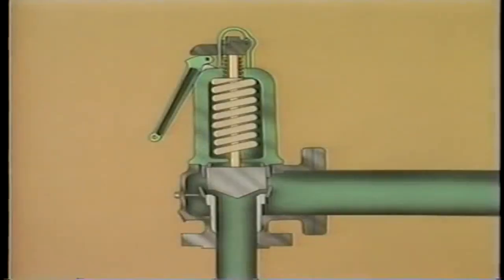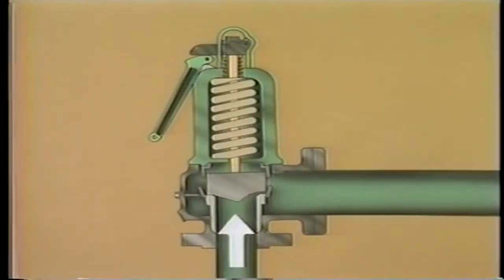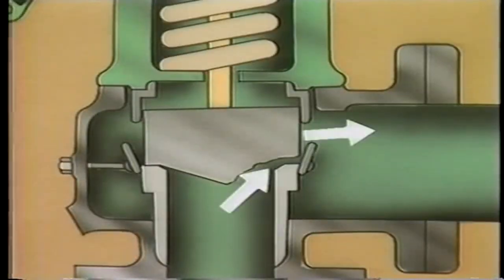Safety valves are necessary to protect the boiler from damage. However, they sometimes cause an operator some problems. The common problem associated with safety valves is leaks. As we've said, once pressure is reduced by the safety valve, the valve will automatically close. However, the valve seat or disc can be damaged when a safety valve lifts. If this happens, the disc will not seat properly and the valve may leak.